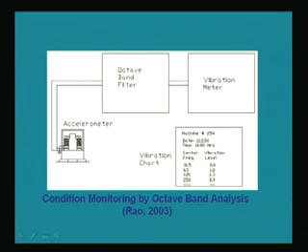Other frequencies we are eliminating, because as I already told, various machine elements give different frequencies. Rolling element bearings, if there is a fault in them, give frequencies much higher as compared to gears. So, if we are measuring the vibration at different frequencies, and at those frequencies some of the level of vibration is high, we will have some idea which member is failing.